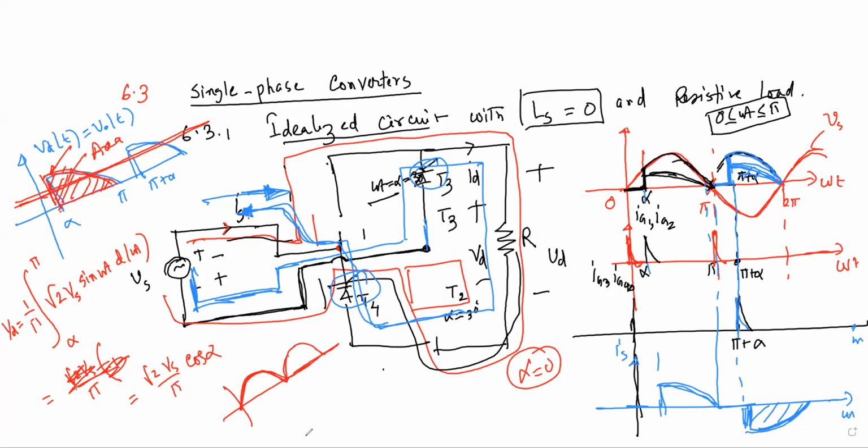And okay, so by varying the alpha, that means the phase control, what is the range of varying? You can vary the alpha from 0 to pi. Yeah, 0 to 180. Good. So by varying this alpha, we can have the controlled voltage. Okay, you got my point or not? Yes, sir. Good. Hey, how about the other students? Shout. Yes, sir, we got it.